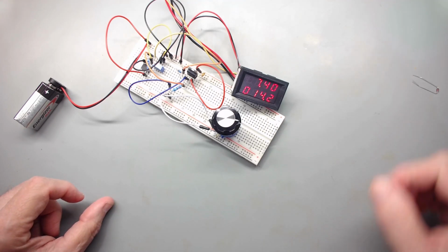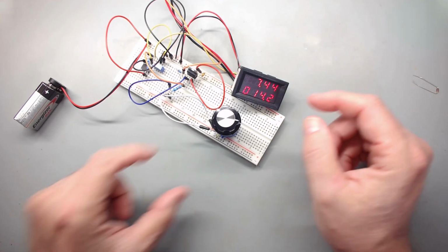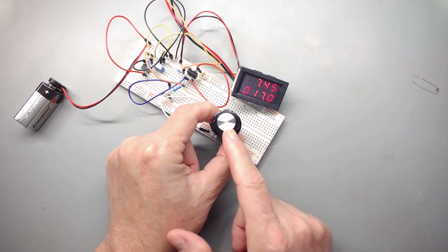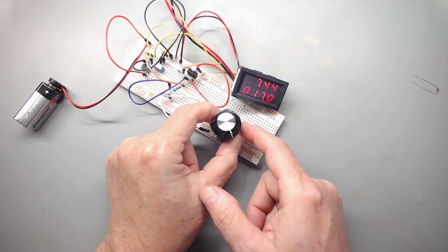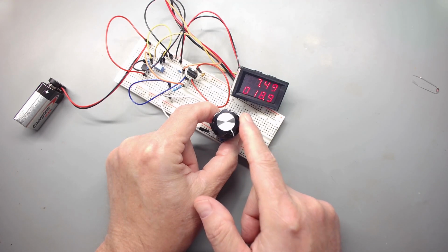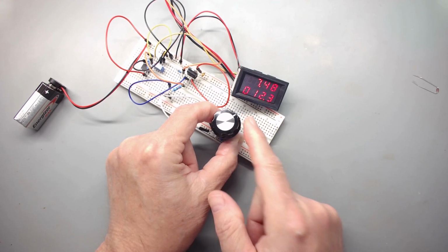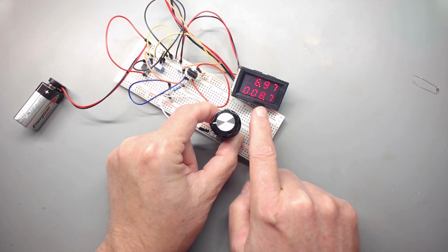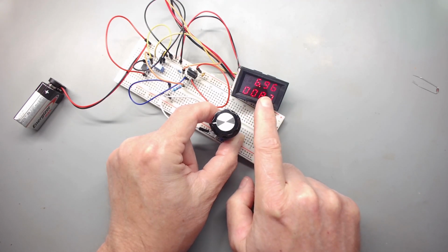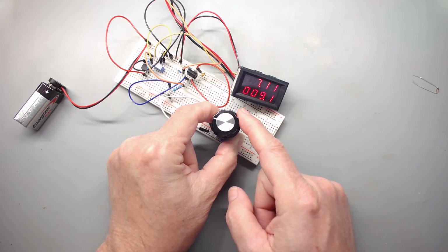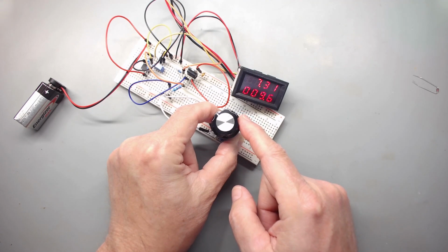And what you're seeing is, let me adjust this knob. This is our potentiometer. Now this is a multi-turn because I've had experience with these types of circuits in the past where I know it's very difficult to tune them accurately with a small 270 degree potentiometer. You're looking at your milliamps at the bottom of the screen here, and you're looking at your voltage that's being measured at the top. So if we take this to 10 milliamps, as so,